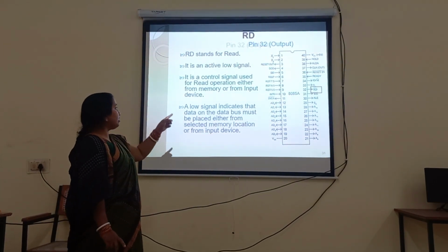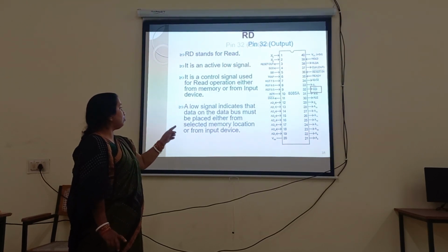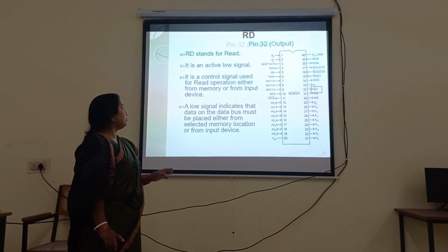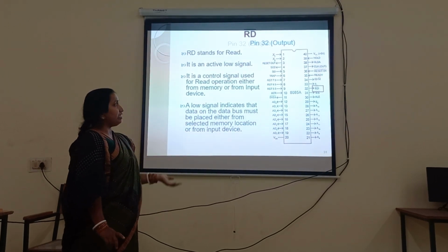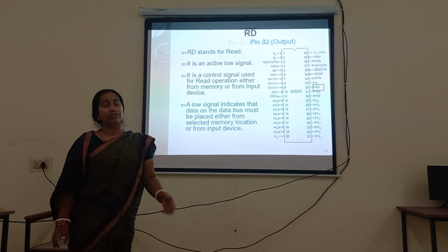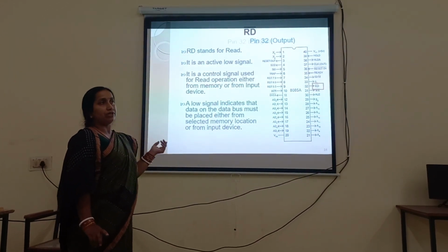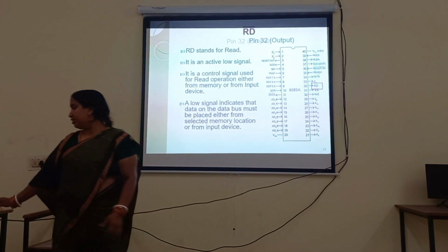A low signal indicates that data on the data bus must be placed either from the selected memory location or from the input device. So here low indicates that there is an operation, a read operation, which is done by the microprocessor when it reads the data from the input output device or memory.